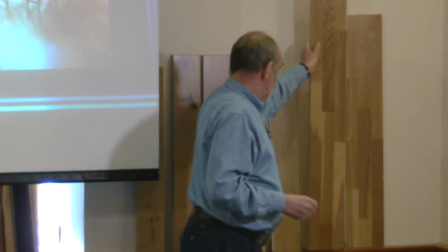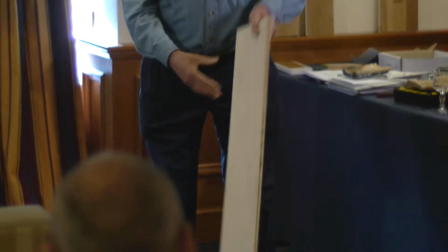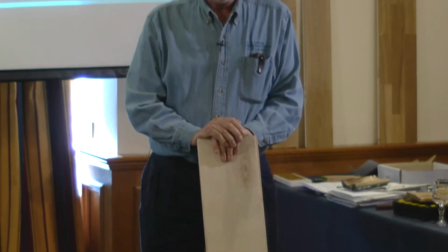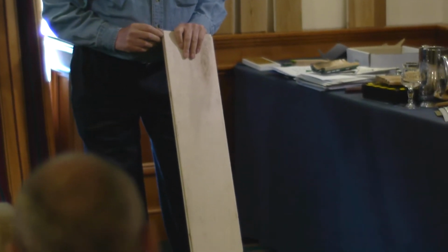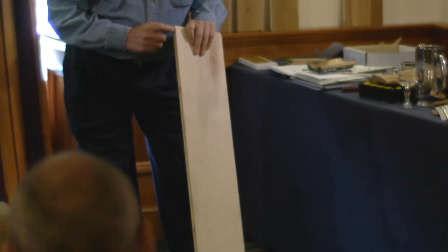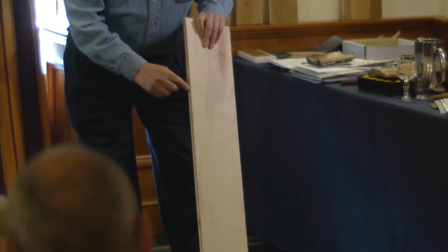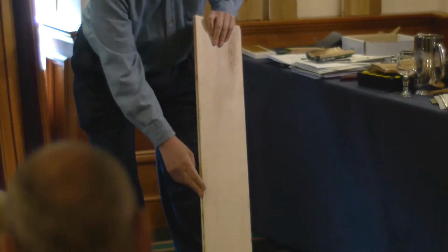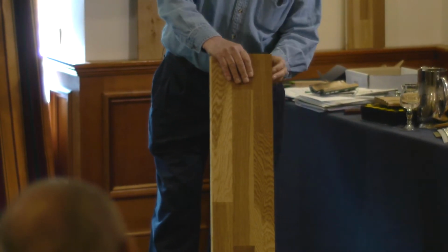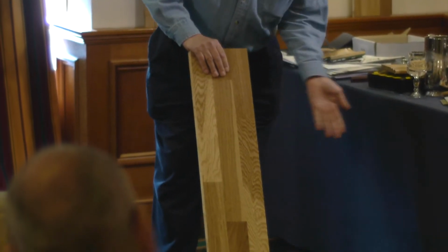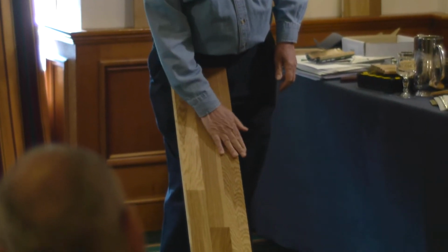Brian, you were saying you were interested in different ways of laying floors. What I see done very well is people floating a wood floor by turning a board over like that. I don't know what you guys do, everyone has a different way of doing it. What I've seen and liked is people will put in, say, glue for about 8 inches, gap 8 inches, glue 8 inches, and it's done like that. And when you turn it over, gravity simply drops the glue down. You put in your tongue, and you have room on either side for the glue to spread out, not to come up on the surface. And it's enough glue to hold a floating floor.